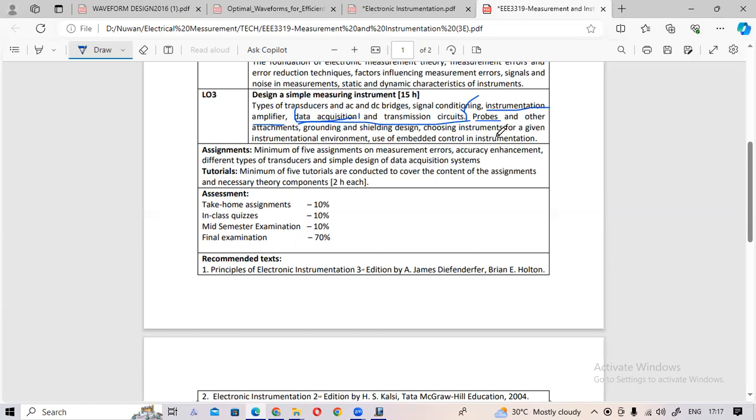You can see that in oscilloscope probes also there is an attenuation switch. That is 100 times, 10 times or something. If you put it at 10 times, then the signal on the other side is attenuated by 10 times, or 100 times. So when you are selecting probes, especially for signal test instruments, you need to see this.